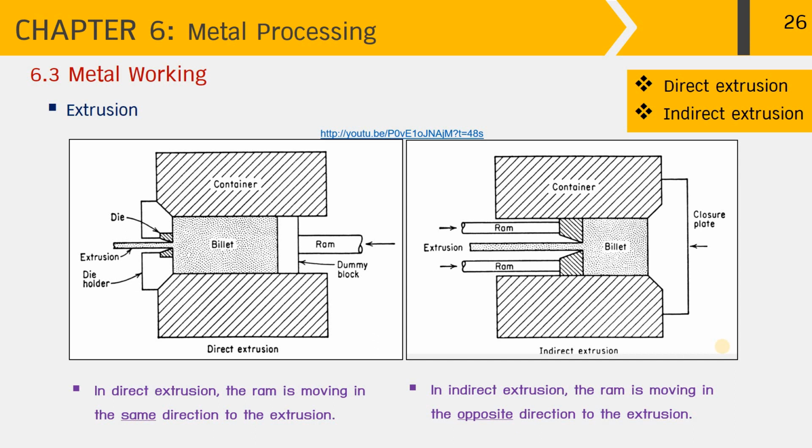The key properties required for metal extrusions are ductility and not too high strength, for example, aluminum and steel. So in the case of high strength alloys, we have to increase the temperature in order to bring down the yield point and make the metal softer, so that the metal will experience recrystallization to make the metal more ductile as a result of finer recrystallized grains.